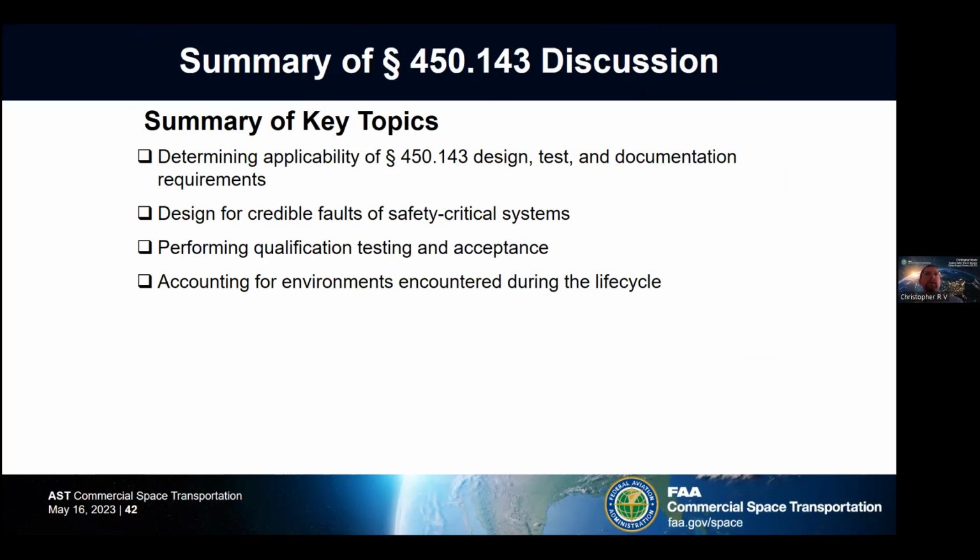To summarize, the key topics of 143. First, you have to determine the applicability of 143 requirements. You have to design for credible faults of safety critical systems. You have to perform qualification testing and acceptance. And you must account for environments encountered during the life cycle.